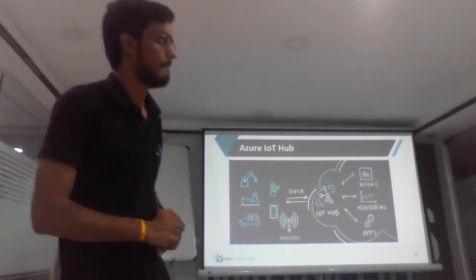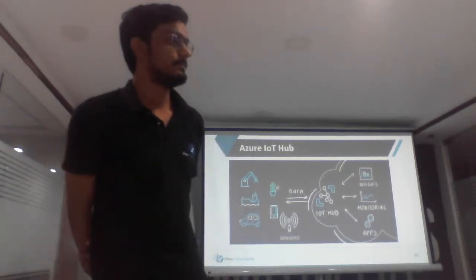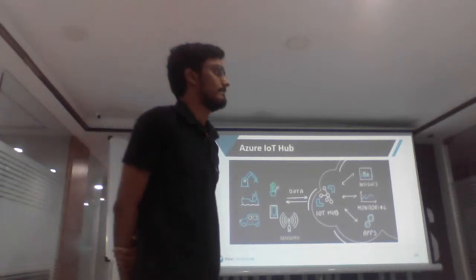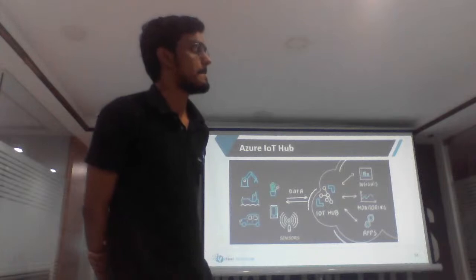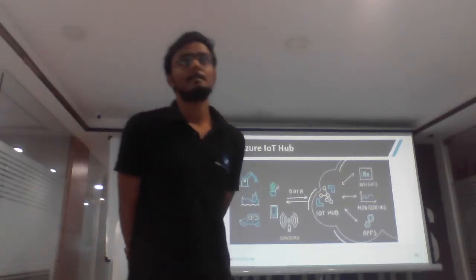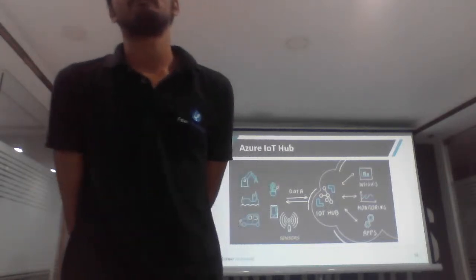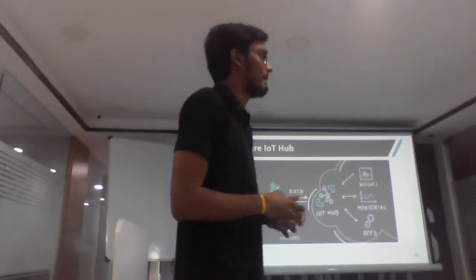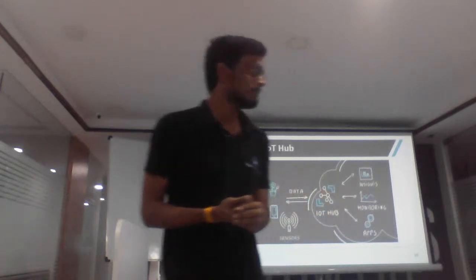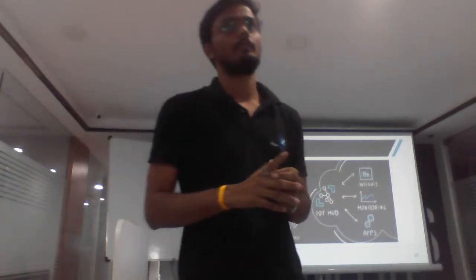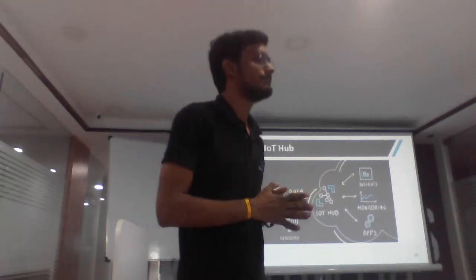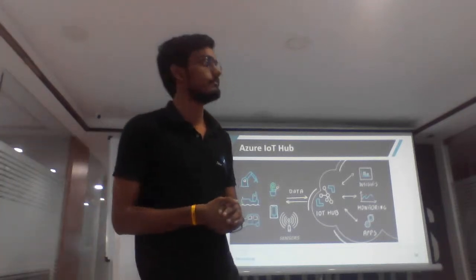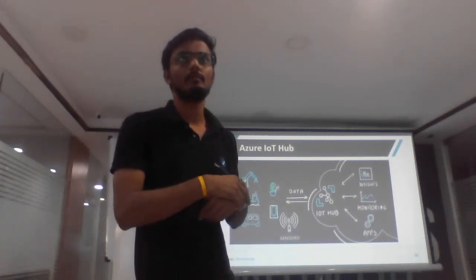Actually, in IoT Hub, say we have a device, currently a temperature sensor. Azure will provide one environment, and we virtually host the device to the IoT Hub. In the script that Ishan has previously shown, we have a connection string. The connection string is for the particular device that we host in the IoT Hub. I'll give a demo so it can be easier.